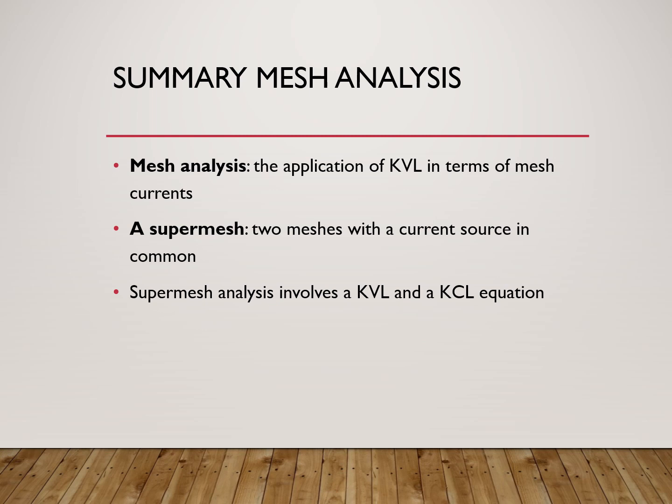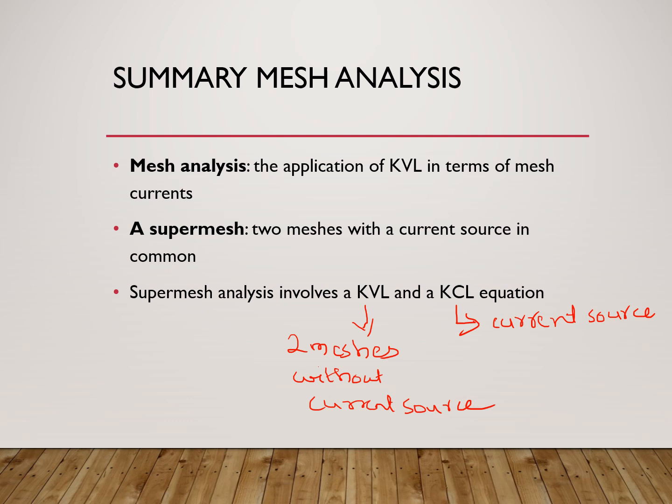The KCL equation is used for the current source, and the KVL is for the two meshes without the current source. With the current source excluded, you write KVL for both the meshes together in one equation. So we have got a KVL for the supermesh.